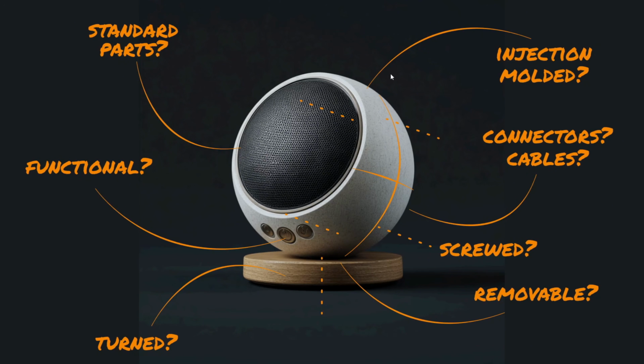So if I were to make this, I probably would make this as an injection molded part with a parting line going from the bottom of the sphere all the way to the top. And then we have a parting line here. And then we could potentially screw it from the back with the dashed line here. But then we also would have holes where the screws have to fit through, right? And also we would require some sort of connection between the sphere and the base. Maybe it's just a magnet and then it just falls into place, but how can we ensure that the orientation of the thing is correct? Or if it's fixed, then we need some sort of fastening mechanism, maybe a click, maybe whatever.